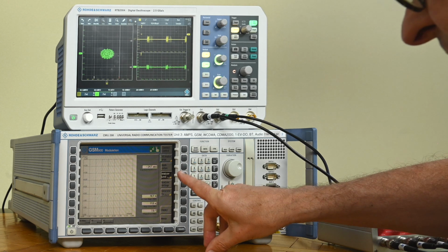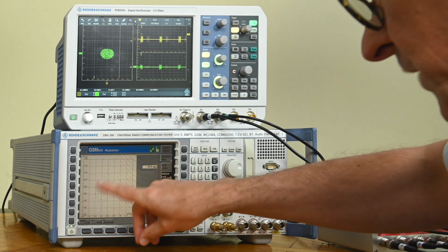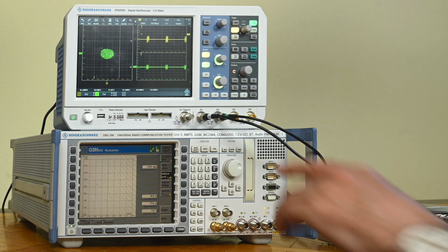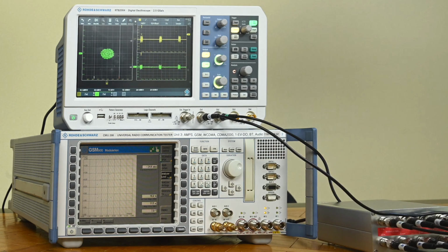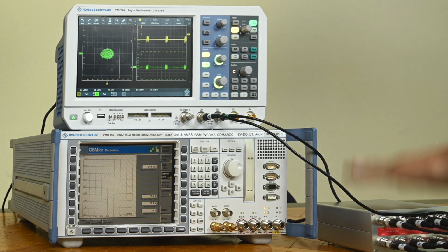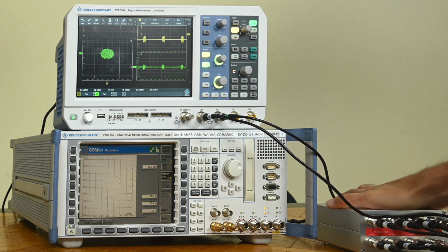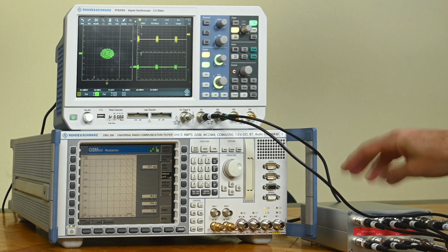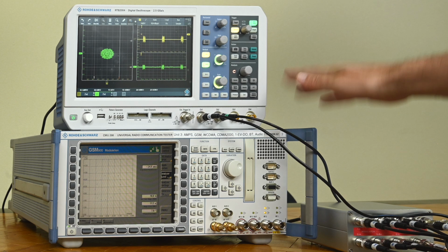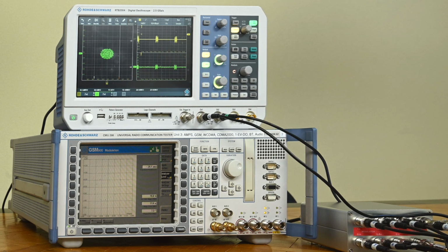And now I got my picture back here at 1500 megahertz, and you see it's distorted to the other direction. And okay, this relates to an issue I've been having last week already. I had the feeling that the I and the Q signal were reversed. I checked this box here 10 times whether it was properly wired. I checked the CMU pin out, etc., whether that was all properly done. I just couldn't find what was going on.